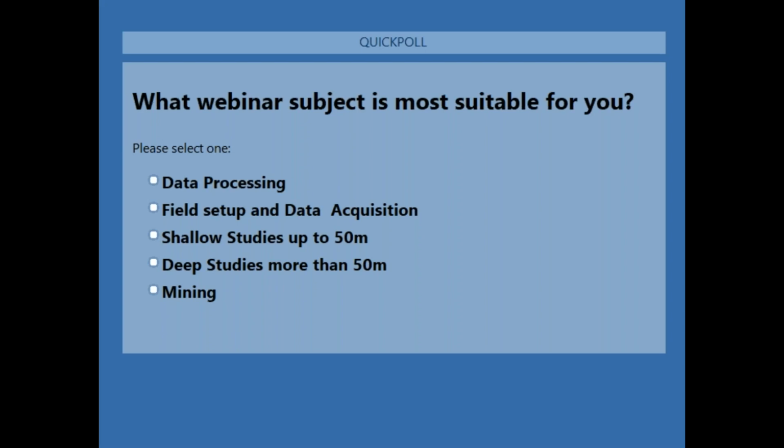So if I have a 1 meter electrode spacing or a 10 meter electrode spacing, then my maximum resolution is 5 meters. If I'm moving and my lateral sampling is every half a meter, maybe corresponding to one data point, that doesn't increase my resolution, it only increases my data coverage laterally. But in the resolution sense, it is half of the electrode spacing.